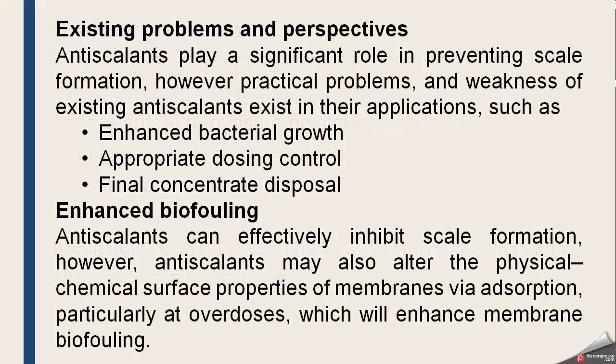Now, existing problems and perspectives. Antiscalants play a significant role in preventing scale formation, which we already know. However, there are certain practical problems and weaknesses with the addition of these antiscalants. Some of these are they can enhance bacterial growth on the surface of the membrane. Appropriate dosing control is a very important issue, and final concentrate disposal nowadays is also becoming an important issue.